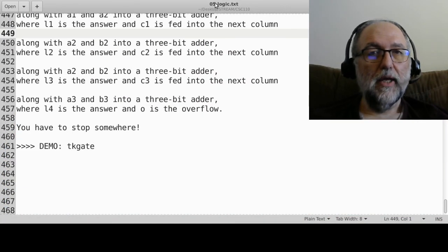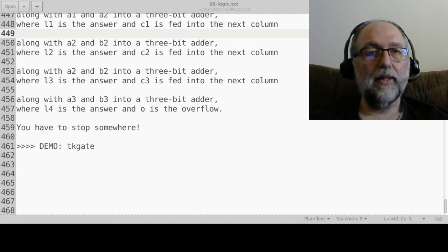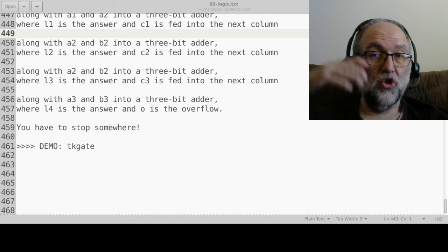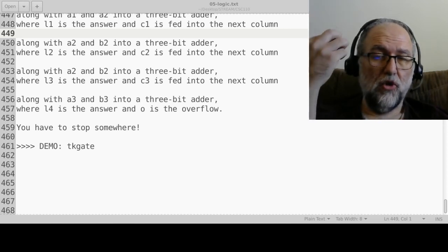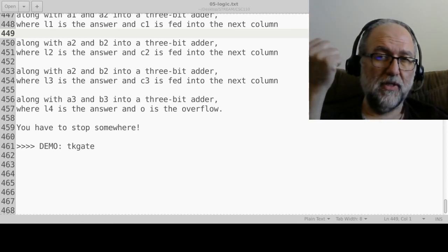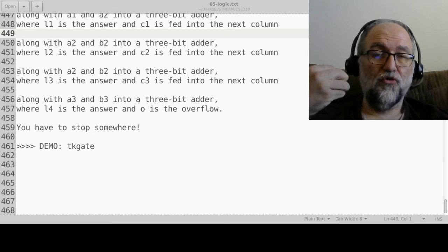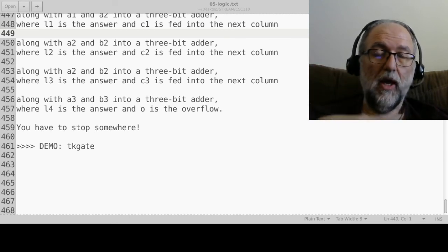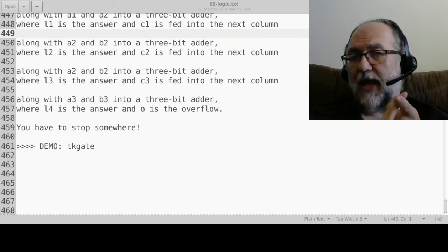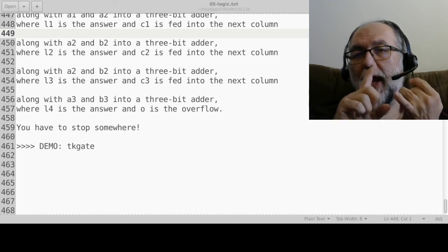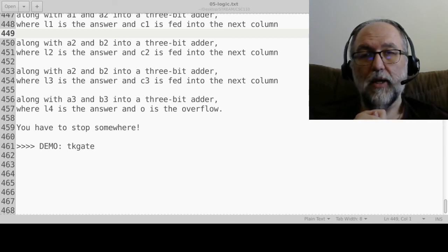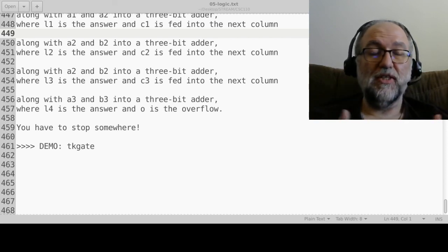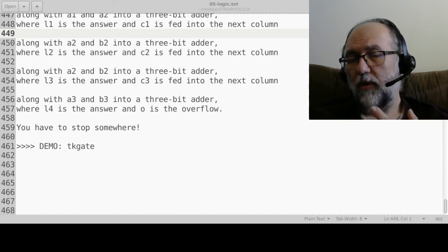That's the end of this lecture. And let me just quickly summarize what we did here. I showed you binary logic, first in terms of just logic in terms of sentences, and then I showed you how that worked in terms of ones and zeros, and I showed you how the binary operators and, or, exclusive or, and not worked. Okay. Then I turned to arithmetic, and I showed you how 2-bit addition is actually an and and an exclusive or.